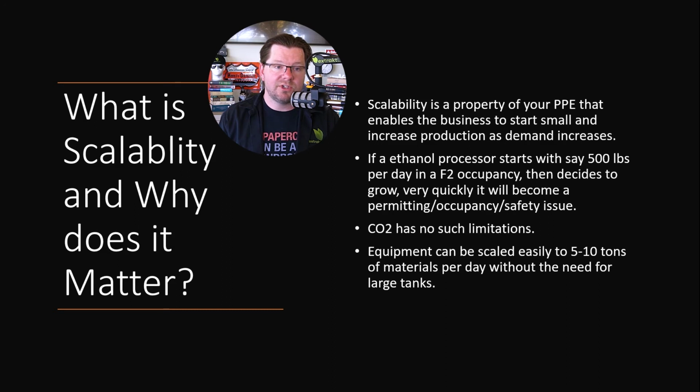So CO2 has no such limitations. You can have an unlimited amount in your building. It's an inert gas. There are things you need to do just from an alarming standpoint and also venting standpoint. In the event of a leak, for example, your alarm would trigger a contact closure, which would give you a vent fan. The vent fan requirement is about 1 CFM per square foot. So that's typically if you have a room where you have your CO2, basically you can vent it out. 2,000 square feet would be the size of like a bathroom fan.